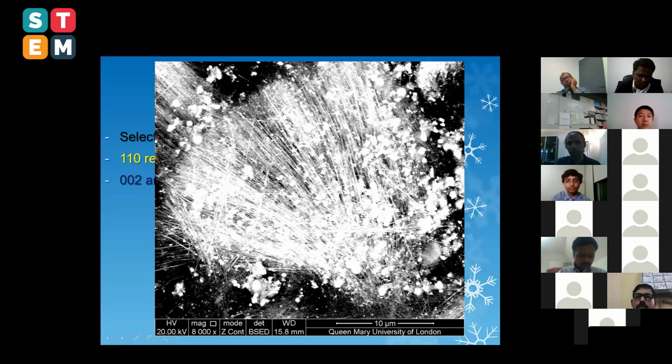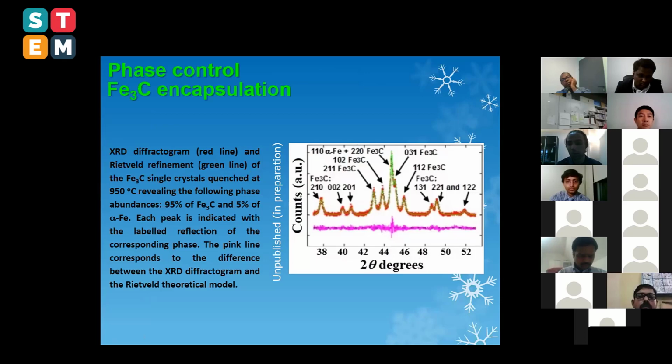So as I said earlier, in order to avoid the formation of the iron oxide phase, we rethought the cooling step, and instead of slow cooling the sample and annealing it, we basically thought about a two-step cooling. A first step consisted in bringing the temperature down at the natural cooling rate of the furnace, from 990 Celsius to 950 Celsius, for example, in this case. And then after this, we applied a quench, which means that we created a rail system. So we dynamically removed the furnace.